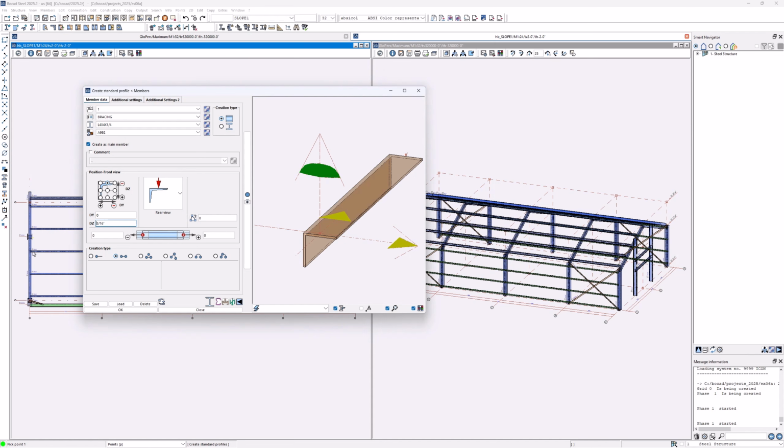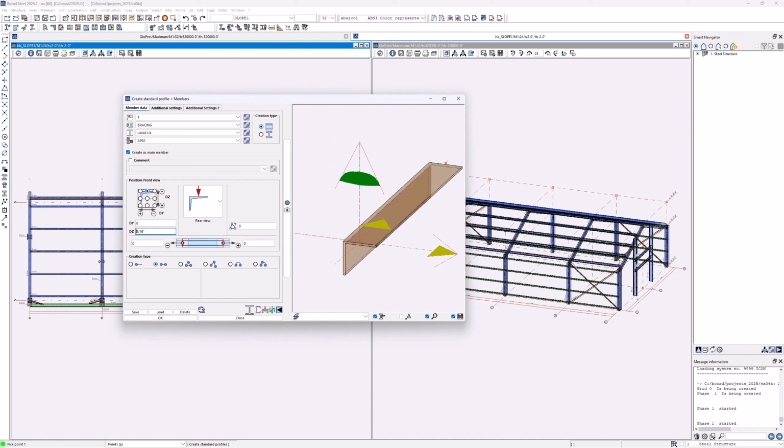Then I have to consider, what is this member? So we have this rafter. The rafter is a W12 by 35 that has a height of 12.5 inches. I would have to say minus 6.25 inches plus 3/16, and then we can already start with all kind of math. I could also say we'll create it like this, and then we'll move it, certainly.